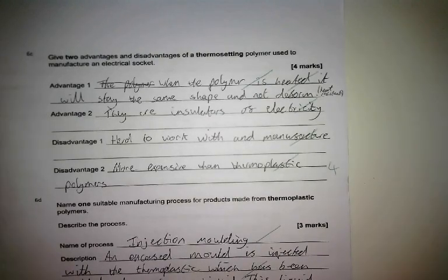Okay, so we're looking for answers that aren't flipped. So an advantage is not the opposite of a disadvantage. You don't want to just say it's a good insulator and then for your disadvantage it doesn't allow it to warm up, for example. So advantage being it's an insulator, low thermal conductivity, so it doesn't let heat build up. It's tough, it's mouldable, it's hard, has a smooth surface, so you're making it out of plastic. It's rigid, so it's going to set solid. Good chemical, heat and electrical resistance.